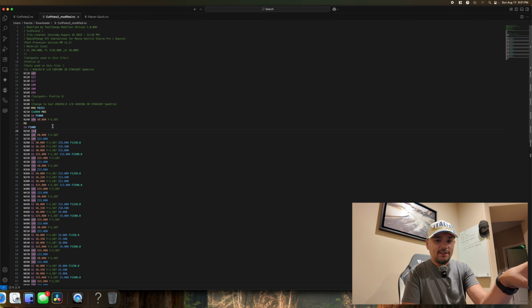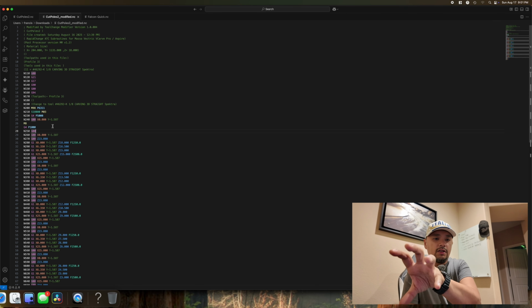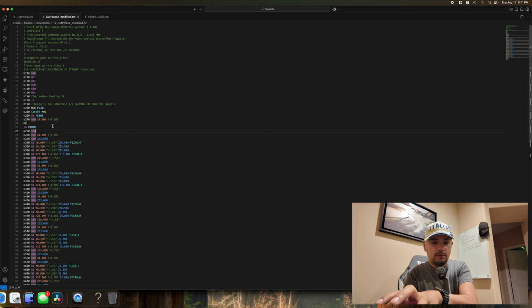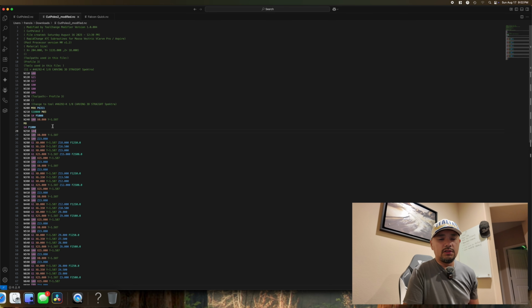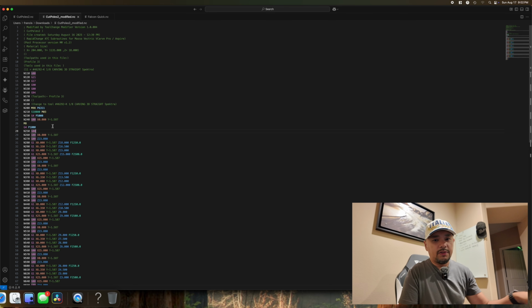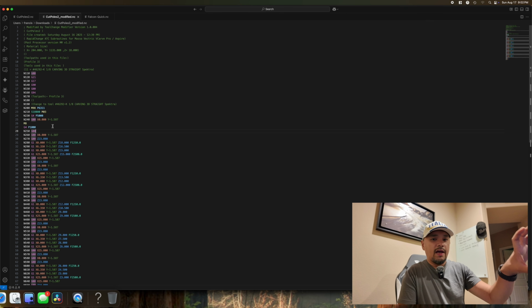Before it moves, it spins the spindle to the RPM we desire for continuing the job. Move to the X and Y, and then the AutoDustBoot will go down, and then the spindle goes down, and it resumes the job. That sequence will avoid hitting any clamp, like a very high clamp that you have on your material.